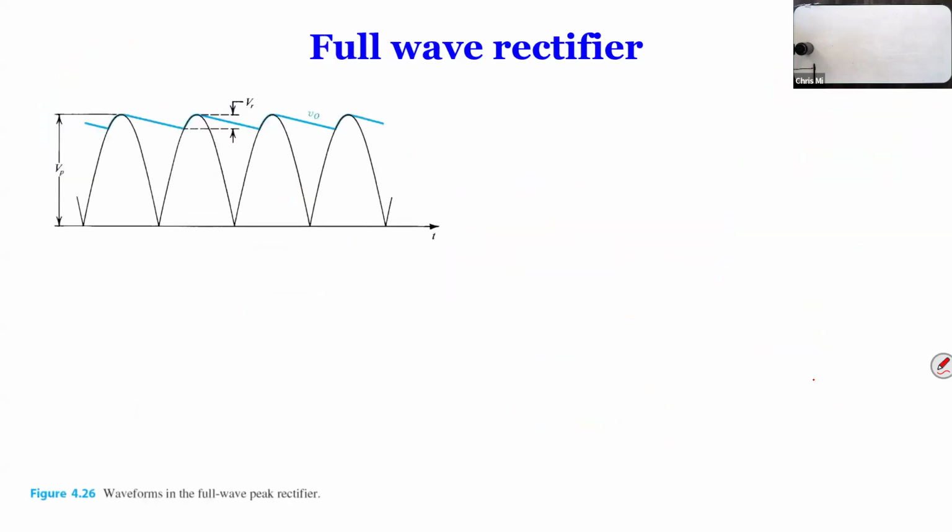If you do the full wave, nothing changes except that the time interval becomes a half cycle instead of a whole cycle. So you can reduce C by half by doing this. This assumption is a reasonable one, because if you look at the blue curve, it drops before it reaches the next peak. So there is a difference between the actual time interval and the half period in this diagram. Your calculated C will actually be slightly less than what you need.